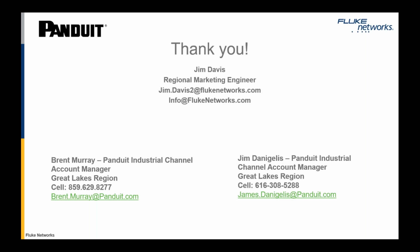The next question here that just popped up is, can you upgrade to Category 6A with existing Cat 5 without replacing and installing Cat 6A? Can you repeat that one again? You can certainly test your installed cable to a higher performance level. The measured insertion loss in the cable is what it is, and we can compare it against different limit lines.